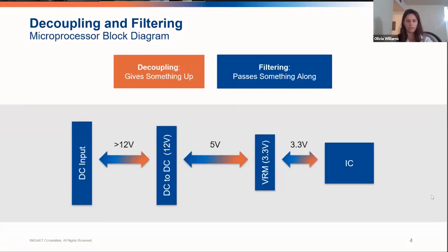Moving towards the IC, where we provide cleaned power, is decoupling; moving back away along the return path is more like filtering. All throughout, we use decoupling and filtering capacitors to absorb and deliver charge as needed, whether it's a lower frequency situation where we need a higher capacitance value, or a higher frequency situation where the capacitance values tend to need to be smaller.